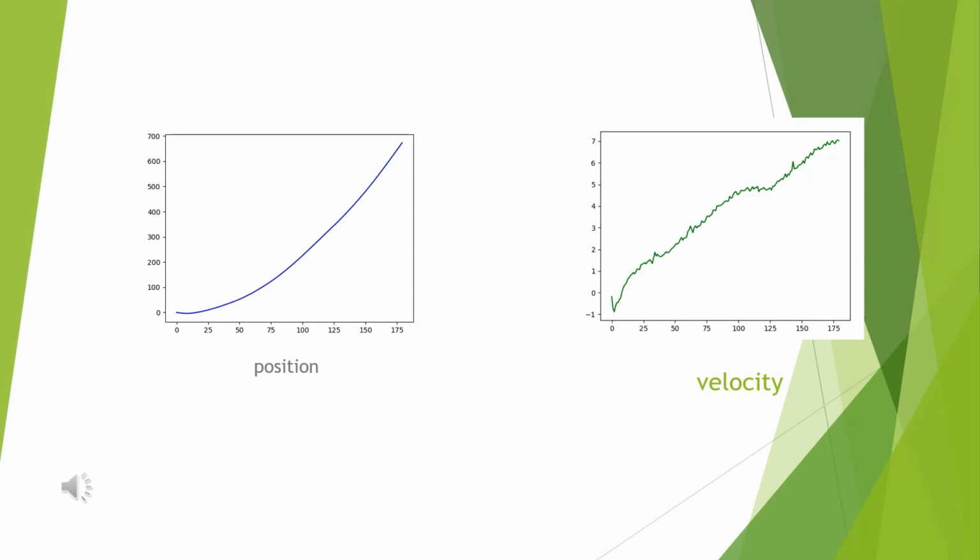By feeding in the acceleration data, we can get this figure. We can see that the data is not accurate because we only walked for about 200 meters. It is impossible to have a value of 700 meters, so we can speculate that the position acquired from the accelerometer is not accurate. The main reason is that we cannot hold the accelerometer horizontally without tilting. The gravity always contributes to the moving direction.